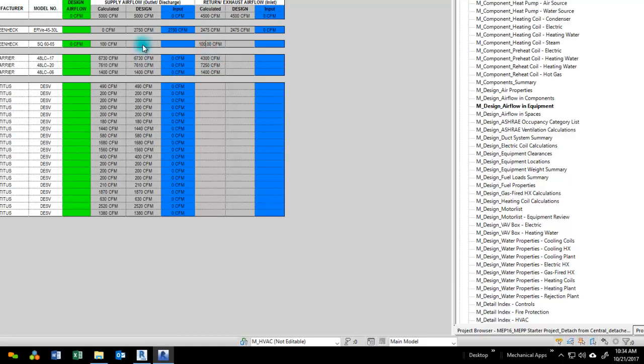However, the schedule is not using these same design parameters. We're not using supply airflow in the fan schedule because, like I said, it could be exhaust airflow, it could be return airflow, etc. So that's where this design airflow essentially is an override for the fans. If your fan design was 150 CFM, you edit that, and then your schedule is using this value.